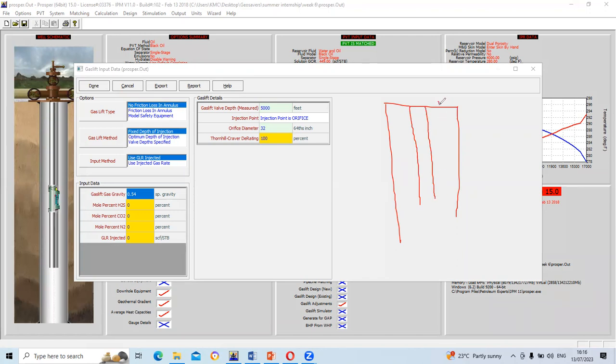Now we are injecting the gas in this space, this annulus space. Remember that at the beginning of the injection, this space will not be empty, because you don't expect that there should be no hydrocarbon inside the wellbore. Before they start designing and implementing the gas lift, they must have shut in the well for some days before they implement all these things and production starts. So some amount of fluid must have accumulated inside this borehole, which under well testing we characterize as wellbore storage.